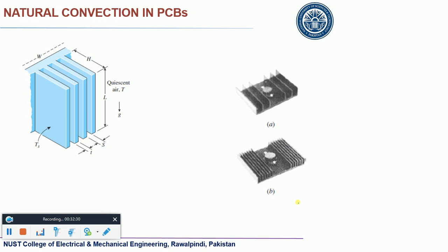Upper one. Why? Why is the upper one the better choice? Yes, it can give you a good amount of flow rate, right? The circuits, or you can say the surfaces, are not closely packed. So it would let the air pass through it with more mass flow rate. But what's the advantage in case of the second equipment?